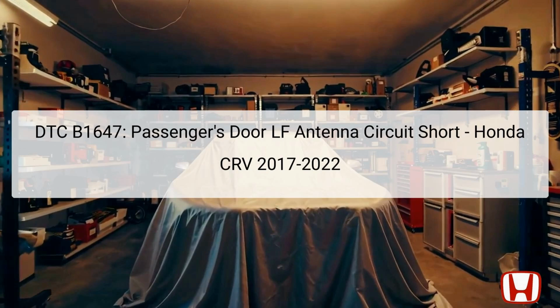The DTC B1647 refers to an issue where the circuit for the passenger's door LF antenna is shorted. This specific error code indicates that there is a problem with the wiring or connections associated with the keyless access control unit of the vehicle.